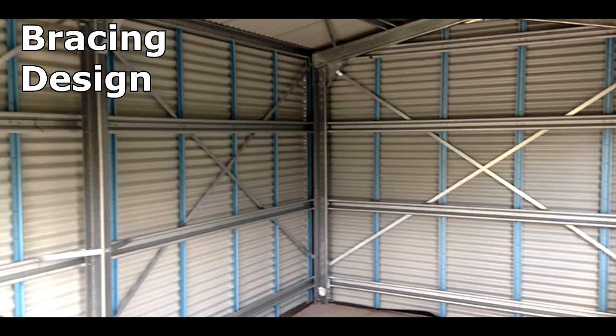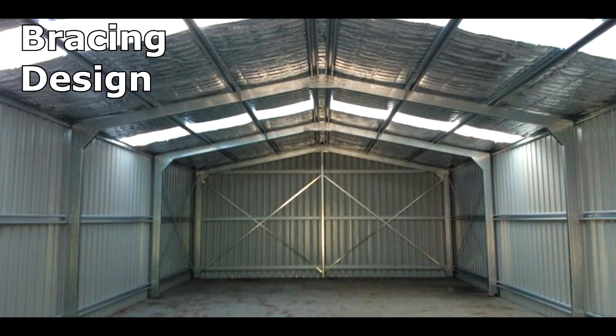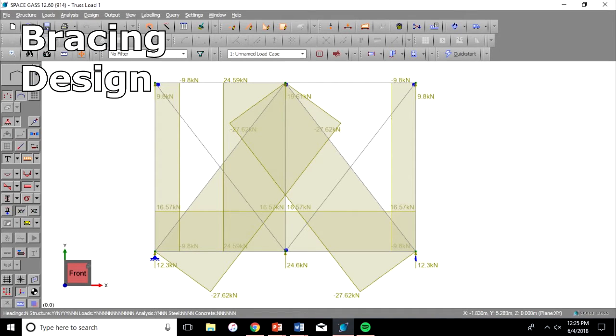While these calculations can be done by hand, the program SpaceGAS has been used to simplify the process of bracing design. In this case, the results found were one wall's bracing design could be a 50 by 50 by 3 equal angle, able to withstand 68.9 kilonewtons of force.